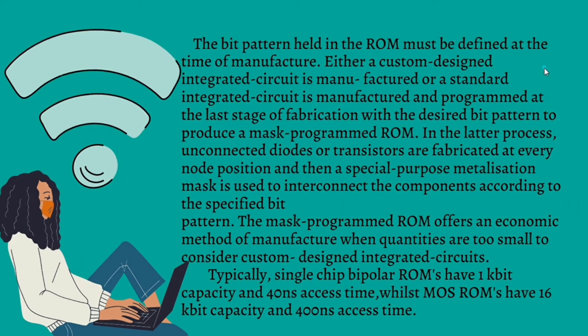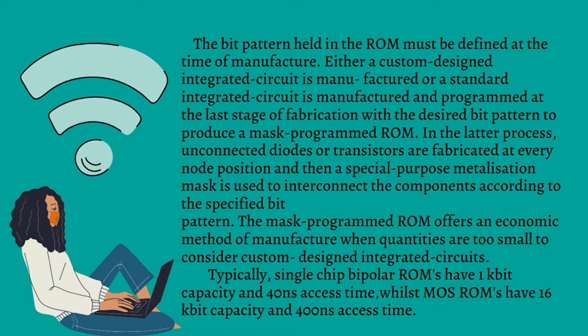The byte pattern held in the ROM must be defined at the time of manufacture. Either a custom design integrated circuit is manufactured, or a standard integrated circuit is manufactured and programmed at the last stage of fabrication with the desired byte pattern to produce a mass program ROM.